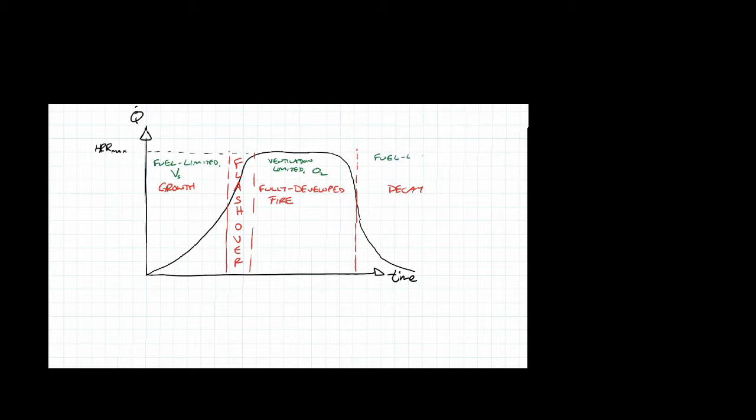That causes the items such as your chairs and your blankets and your carpet to ignite. Now typically the critical heat flux is on the order of around 12 kilowatts per meter squared. Flashover is determined about 20 kilowatts per meter squared. Flashover is the magic point that we need to identify and prepare for. So if we can have adequate fire alarm systems to notify people and means of egress systems to evacuate people prior to flashover, we can keep them safe. If they stay in a compartment after flashover, they will not survive. You cannot survive a flashover without PPE. So that's why it's so important to understand this concept and engineer a way out.